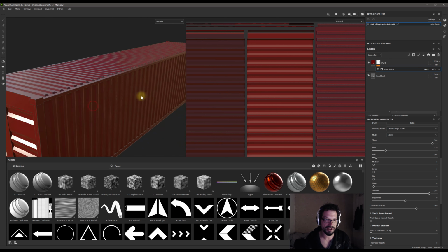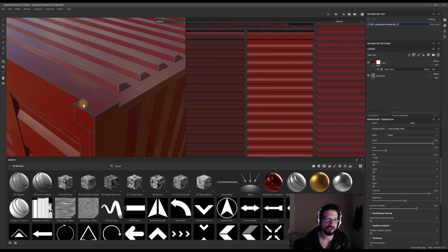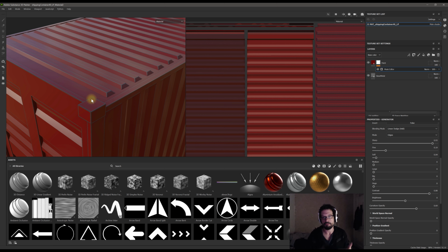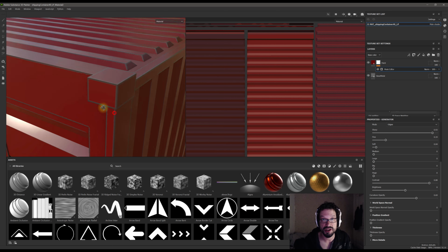Okay, so this is good, but right now, as you can see, we are scratching literally every edge. Everything that is an outside edge is receiving the same treatment, which isn't something we want, because this doesn't look random. We want this to look as random as possible to tell a story. Maybe for some reason in the future, or in your work right now, you might want to use the curvature channel for this kind of work, but in our case, for scratching the paint, this doesn't seem to make any sense, because literally every outside edge is scratched, and they are scratched in the same amount.